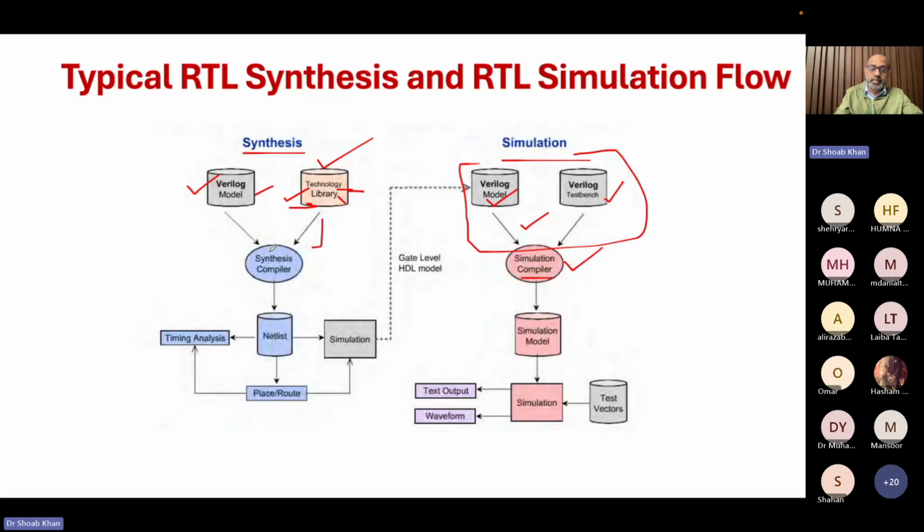So it will synthesize the code and generate a netlist, and that netlist will also be Verilog code. So it'll create a Verilog version of the code for you to take as a Verilog model, and you should still be able to run your test vectors to get the comfort that after your compilation, your system is still working, but it will be very, very slow.